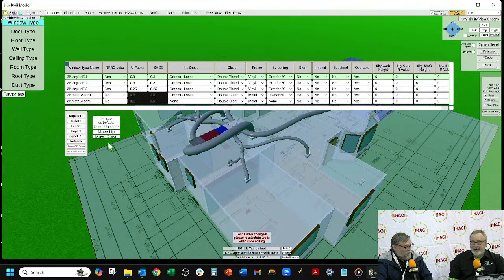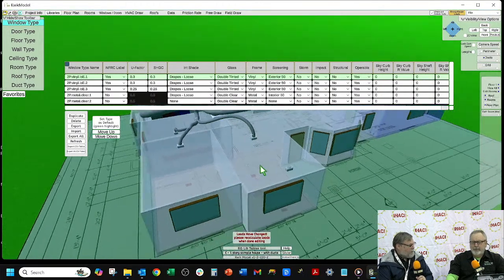Fireplaces too. When I do a blower door, I've seen it where you're sitting there and the pressure is going good, and suddenly it drops. You're like, what? I can't even get a reading now. What's going on? Oh, the door opened up. You have to push the door latch in. But infiltration is probably one of the big factors for older homes. And then of course duct leakage. But here in California, if you replace equipment, the ducts have to be sealed anyway, so you can kind of assume that's going to be fixed. That duct leakage is an important part of it too.